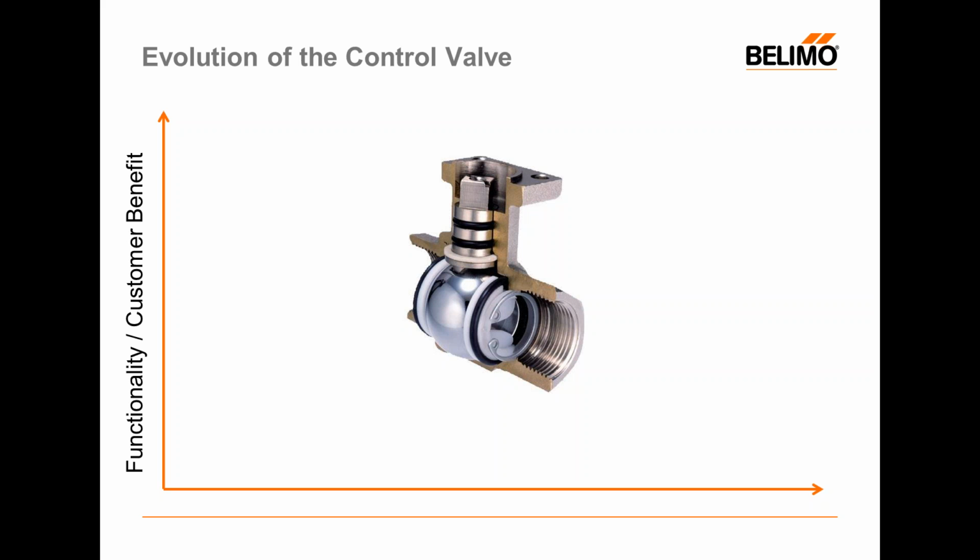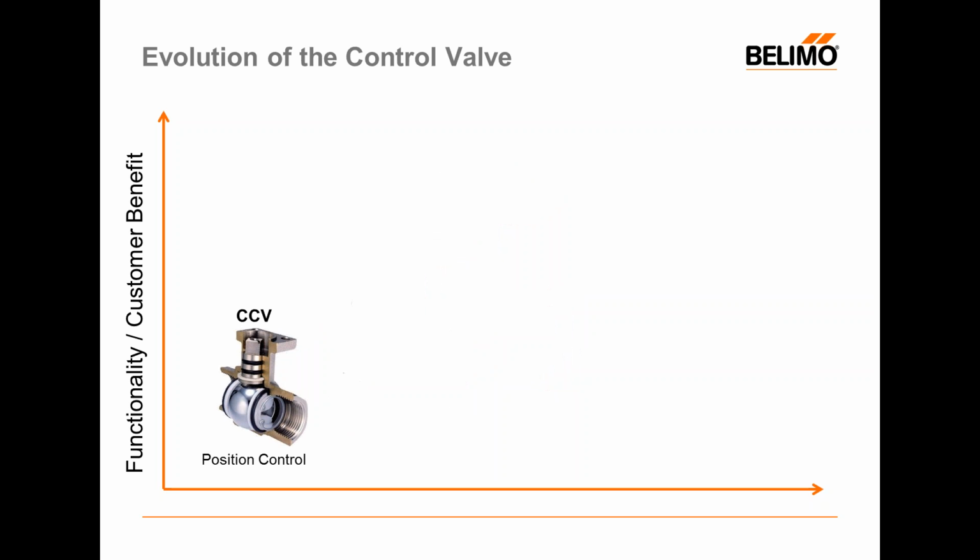However, we can all agree that if I have a specific opening and there's 1 psi of water pushing on that opening, I'm going to get a dramatically different flow rate than if the same opening saw 50 pounds of pressure. Now granted, that's a humongous swing. We hopefully aren't seeing those in our buildings, but it certainly illustrates the point that controlling directly to the position of the valve may or may not have the best value in terms of controllability. And so we'll put that on the low end of technology. We've been using this technology for darn near 100 years, so it's not like we can't figure out how to control a building with it, but frankly there are better options today.